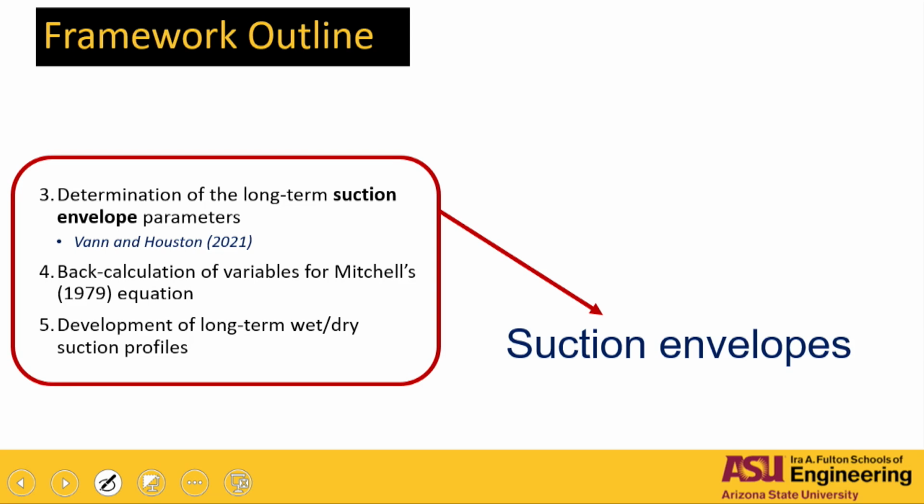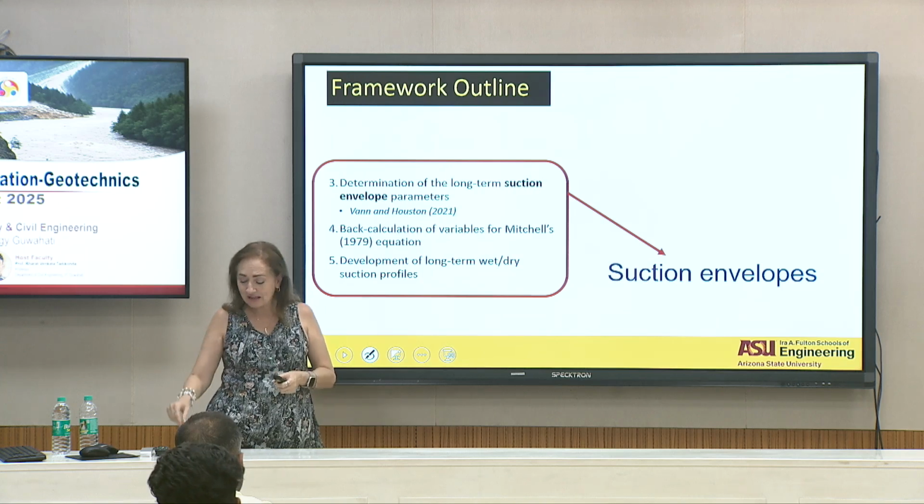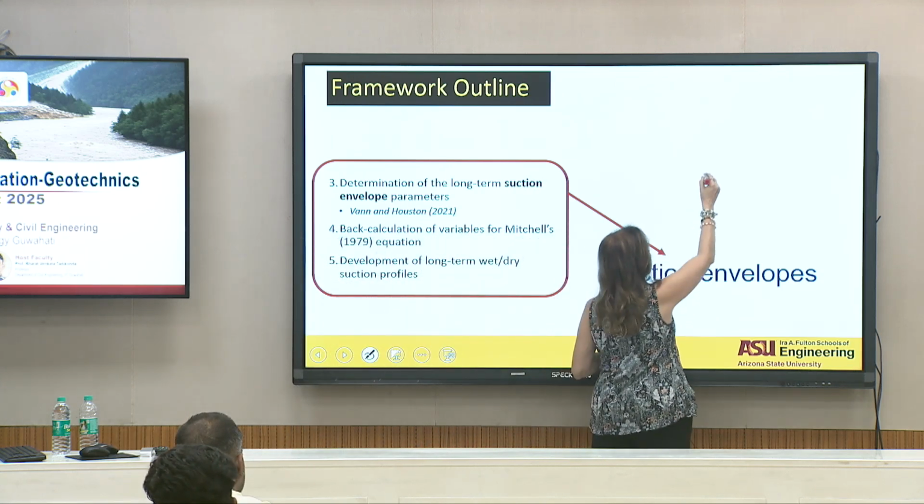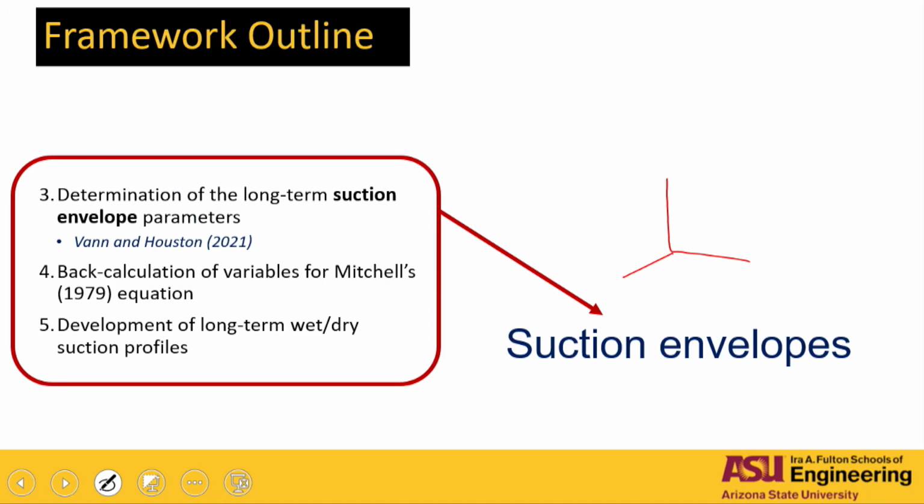Okay, so coming back to our discussion this morning, the constitutive surfaces: we got something like that for compressible soils, right? For compressible soils, when we have a change in void ratio versus either total stress or net normal stress or suction.